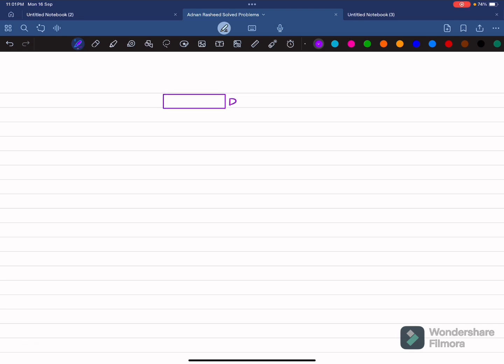This is your point D, this is your point E, where there is a distributed load acting downward, and this distance is given as A. And when you cut it, you will be having a shear force V and you will be having moment M. So we will find this moment at point E. So how will we find this moment?